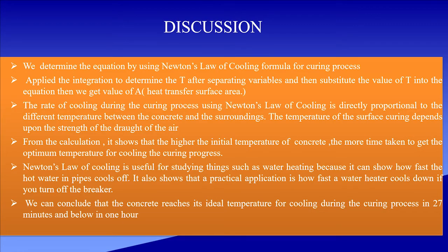Thank you, Muhammad Adha. My name is Muhammad Qayyum bin Razman and I will continue our discussion. Firstly, we determine the equation by using the Newton's law of cooling formula for the curing process. And number two, we apply integration to determine the T, which is temperature, after separating variables, and then substitute the value of T into the equation, then we get the value of A, which is heat transfer surface area.